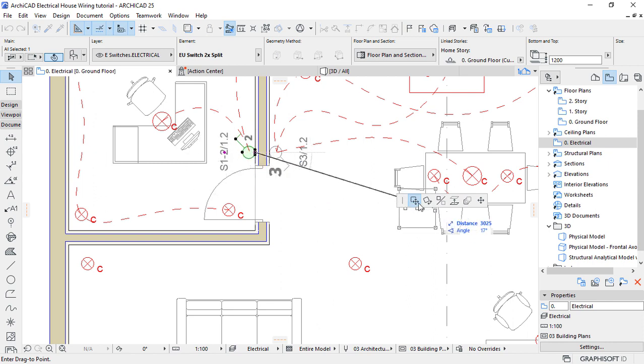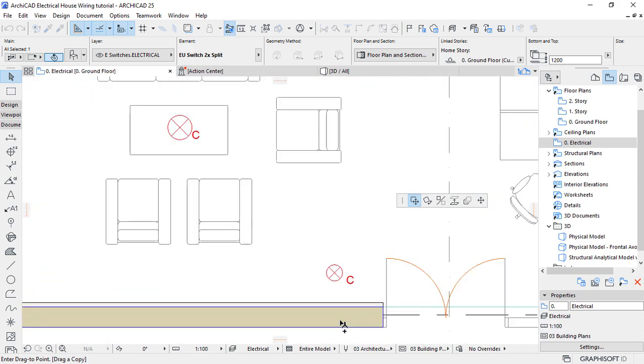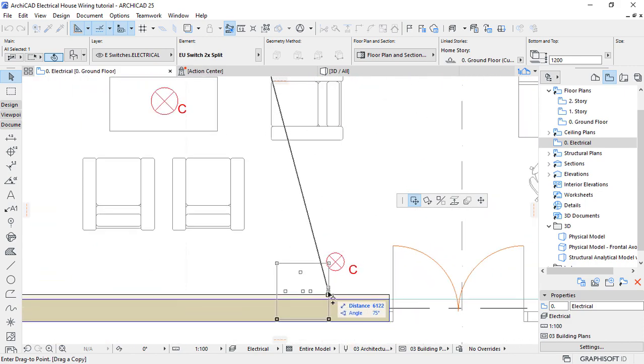Click on the element and then activate drag on the pad palette. From here, you click Control on your keyboard, and then your cursor will add a plus. That means you are carrying now a copy by hitting Control on your keyboard. So I'll move this to here, place it there.